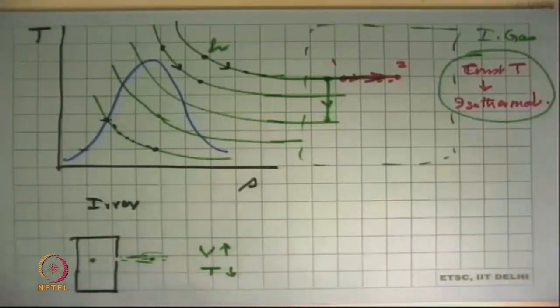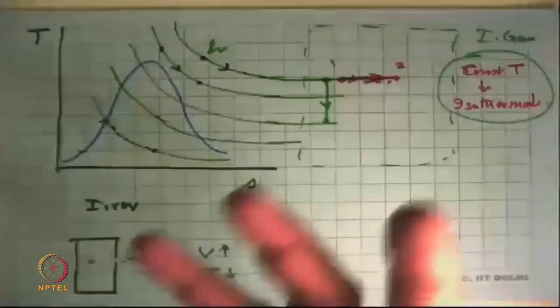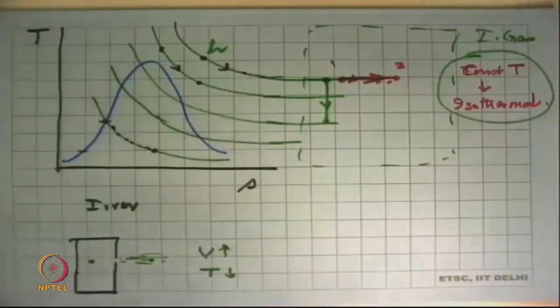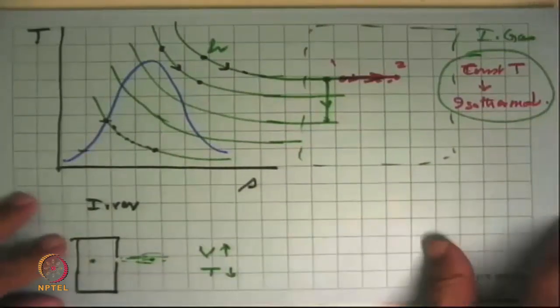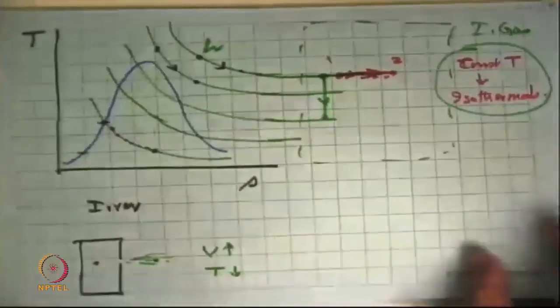So inside the plane, the air is either heated or cooled. If it is hot outside, on the ground, it is to be cooled. So that's what is done. And when you are up flying at 10,000 meters, the air temperature outside is minus 40 degrees Celsius, in which case the compressed air, which is at a higher temperature, is slightly throttled and put inside the passenger cabin to make it nice and cozy. But those are not entirely throttling processes. You are partly using the effect of a nozzle also. Okay, so that was throttling.